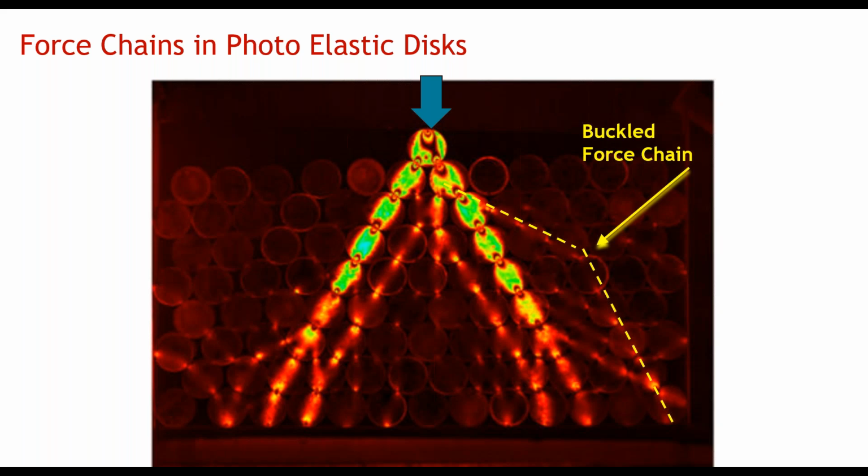If we want to stop this from happening, we need to hold the particles in place. How? Well, we could fill the voids with glue. That's what we do with cement or lime stabilization of soils. The particles are then fixed together and movements controlled. This is how chemical stabilization works, but it has many other drawbacks. So how do we achieve the same thing with geogrid?